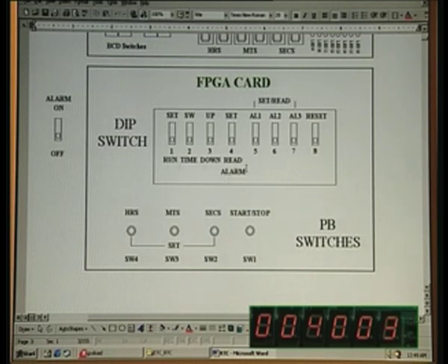So as far as possible, I have retained the very same arrangement for all the switches, except that reset is part of the DIP switch here, and which was shown as a push button switch in the previous layout. And you have hours, minutes, seconds right at the FPGA board's left hand side corner, and they are all numbered SW4 through SW1, and there is one more switch here, so that we may start or stop the up counter or down counter, which we have.